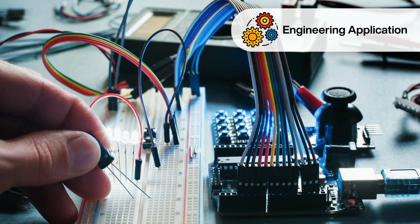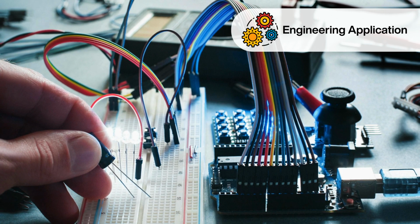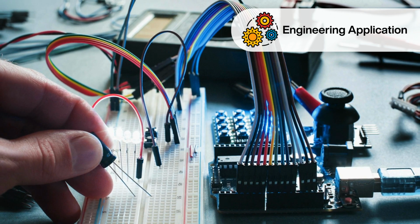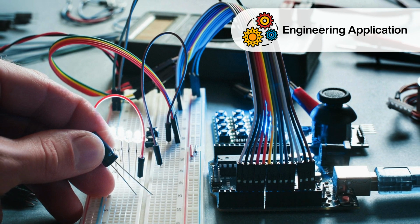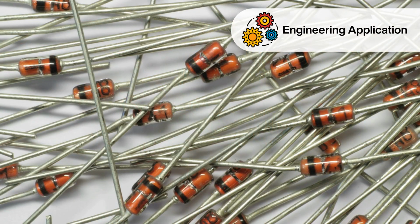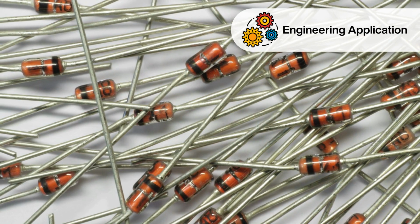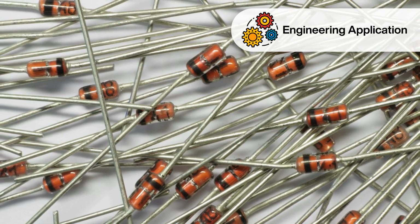Firstly, different components such as resistors, semiconductor diodes, and filament bulbs exhibit unique IV characteristics. Knowing these behaviours enables engineers and technicians to choose the right components for specific purposes. For example, semiconductor diodes with their nonlinear IV characteristics are essential in rectifying circuits that convert alternating current AC to direct current DC.